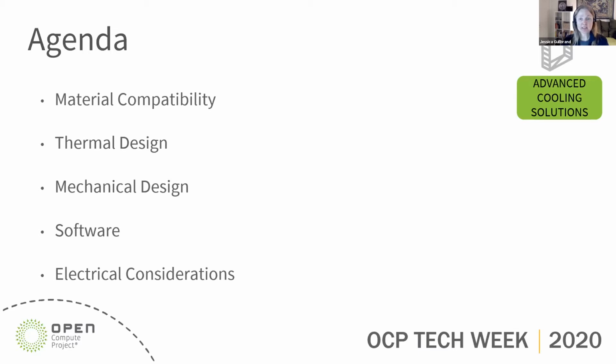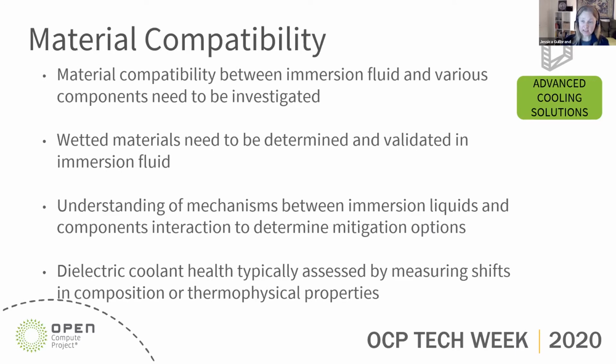So jumping in to material compatibility, as already mentioned today, it's really the foundation of everything when it comes to immersion or any type of liquid cooling in general. You need to make sure that the immersion fluid is compatible with the different components that go into the liquid.